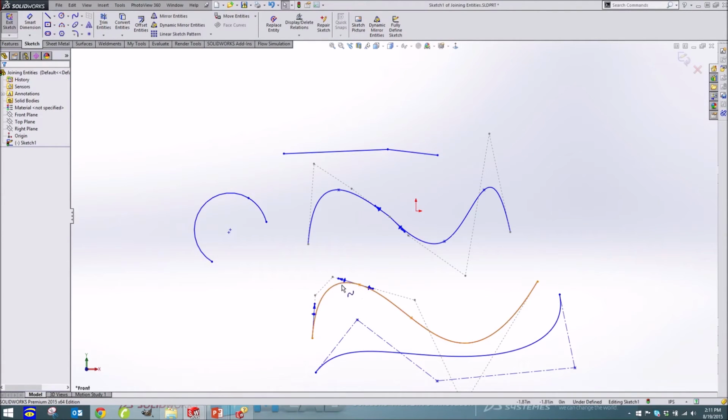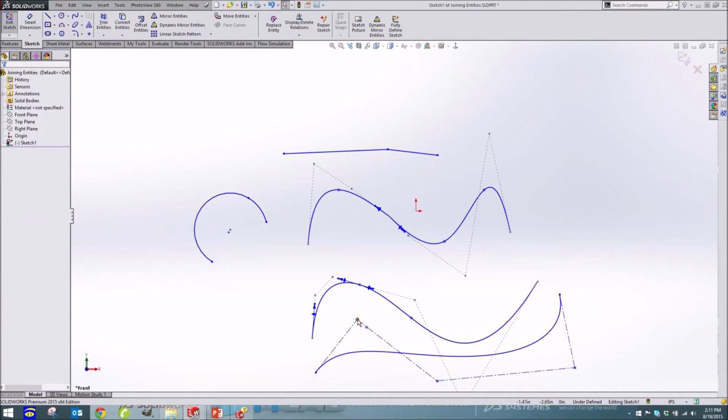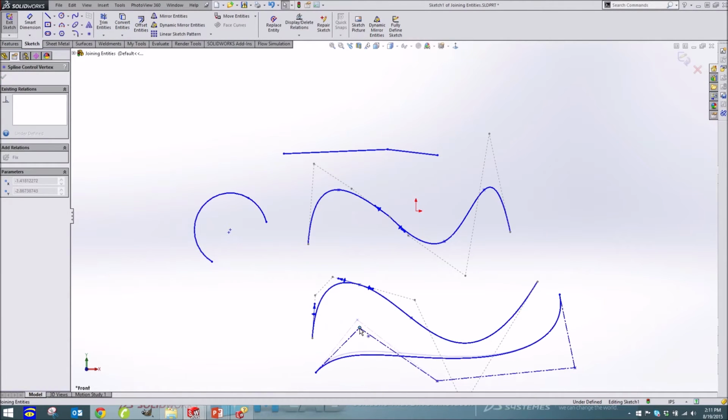On a B-spline, the spline is controlled through each point, or through each series of points. So we've got 1, 2, 3 segments here. On a style spline or a Bezier curve, we have one complete segment. So these are much easier for SolidWorks to calculate. They're much easier to define, and they also lend themselves very well to symmetry.